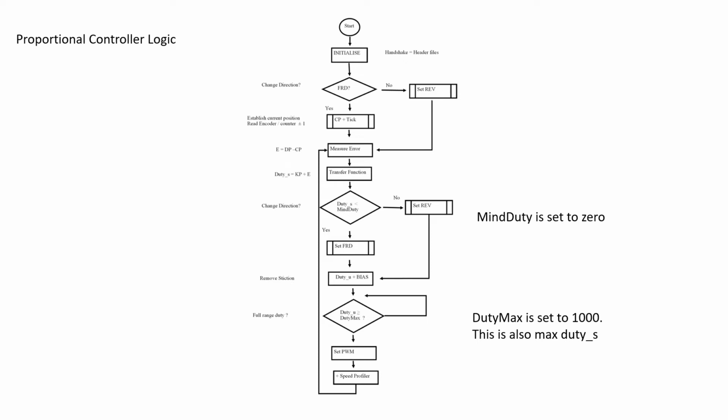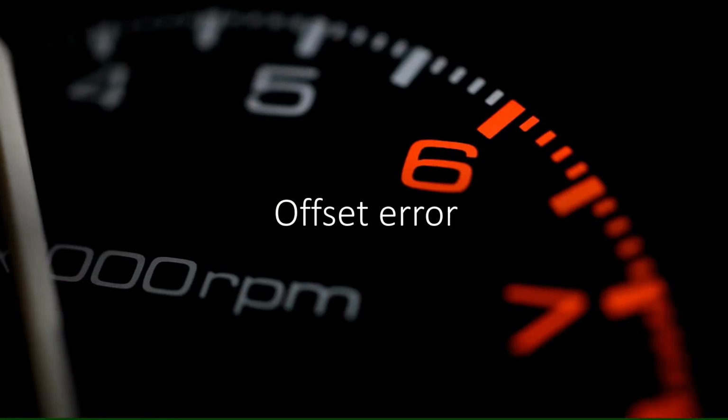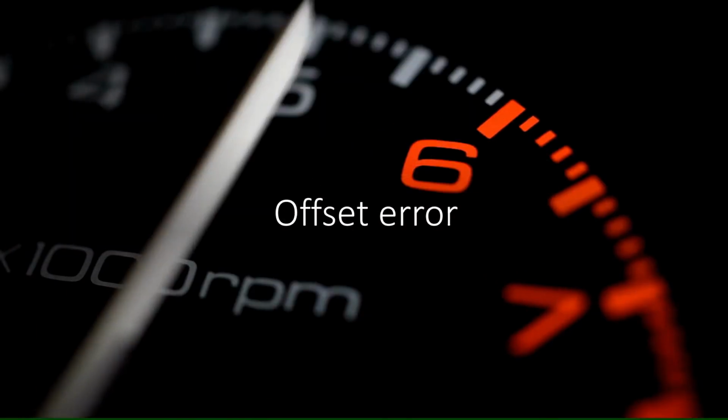If you want it to go forward, it sets the duty forward, it sets the direction for forward, and then it adds the bias to the duty that has been calculated, and then it starts and it checks have we reached maximum duty, and then it sets the PWM, and then it starts moving. And when the speed profiler sets in, that means you have a constant speed. So this is the offset.